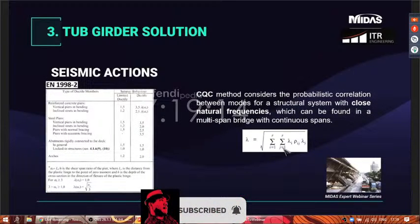Eurocode 8 part 2 requires a behavior factor for limited ductile piers equal to 1.5. Modal shapes have been combined in the model through a complete quadratic combination, CQC, that is more suitable for multi-span bridges with respect to SRSS, that is more commonly used, but tends to overestimate or underestimate the results in a system with close natural frequencies.